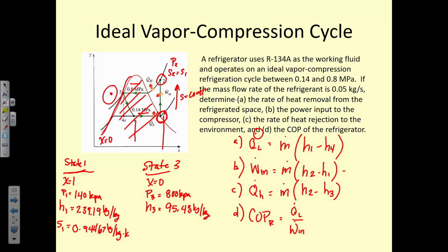If you don't, then you make the compressed liquid approximation: it's not on the line, but we jump over to the line and use the temperature to look it up in the tables. And for the far right, if it's far past the line, it's superheated. We have plenty of tables for superheated vapors. It's just the compressed liquid region where there's only one table, and it starts at 10 megapascals or something like that.